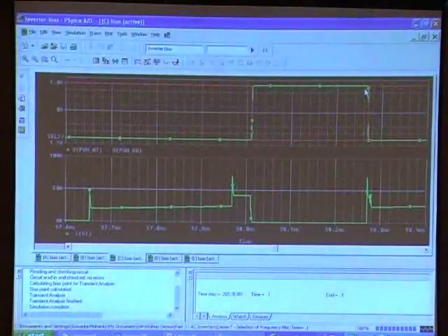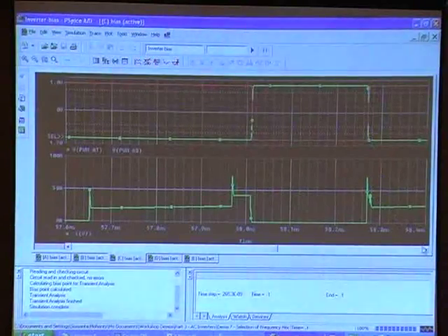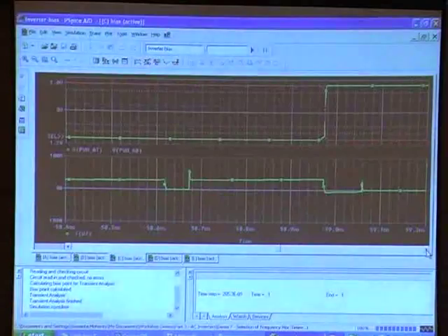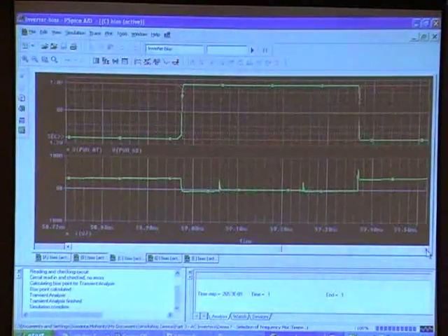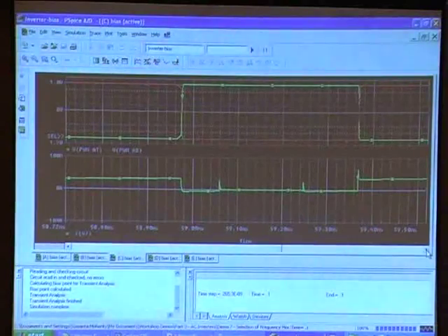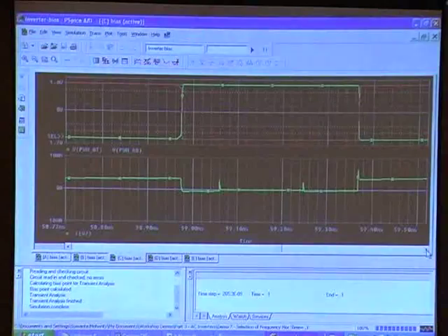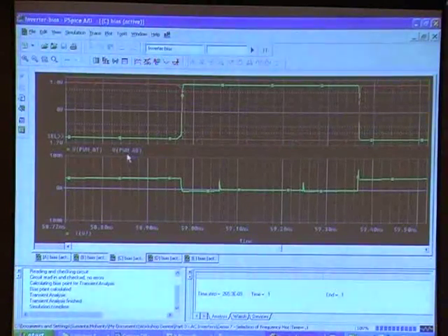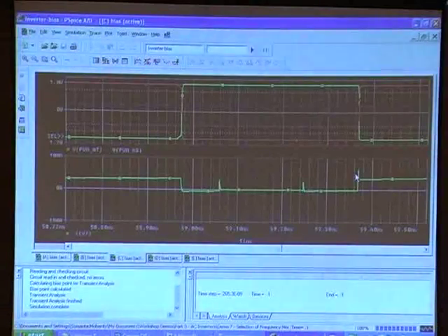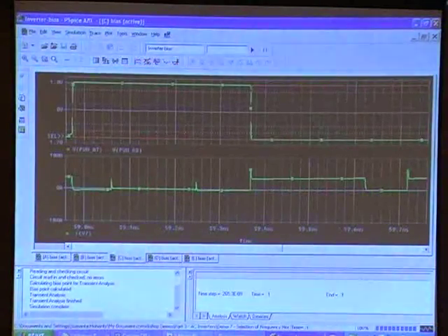So when red is going up and green is going down, we have shoot through here. When the lower one is going into conduction, that time it's going to be true. That's correct, in the lower one. Yeah, that makes sense, right? So when the bottom one is going up in conduction, then this spike happens. Yeah, correct. Okay, so that was a good exercise.